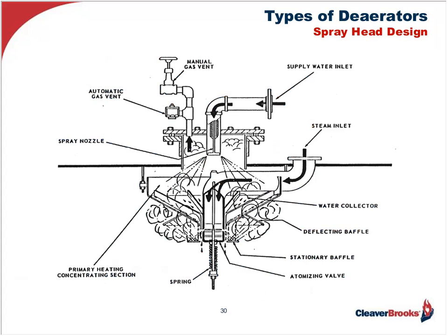As this steam condenses and combines with this hot feed water influent, it collects in the cone and is pushed through the spring-loaded spray nozzle, which is also seeing live steam. And here it's agitated and misting, and the mix will be heated to the saturation temperature, and if we're talking 5 pounds, that's 227 degrees, thereby finishing the deaeration of the liquid before it collects into the integral feed tank. So then the remaining steam after the final stage is condensed, leaving only the remaining O2 and CO2 to exit the vent.